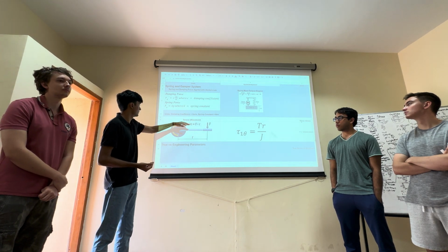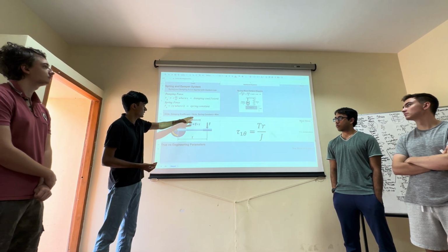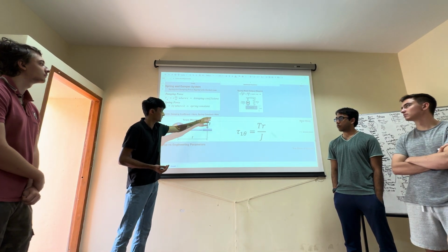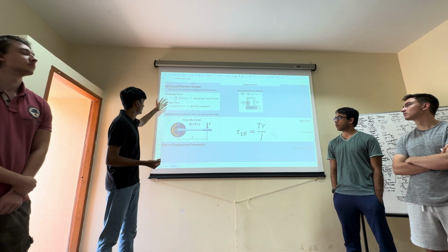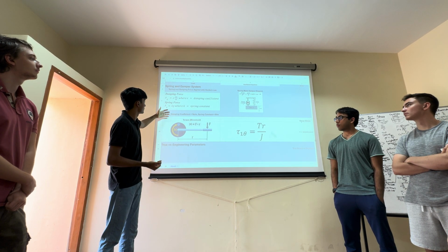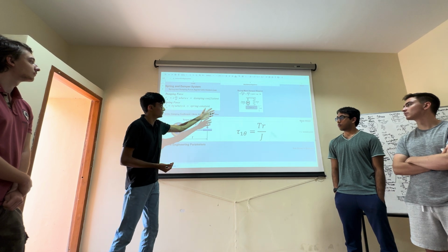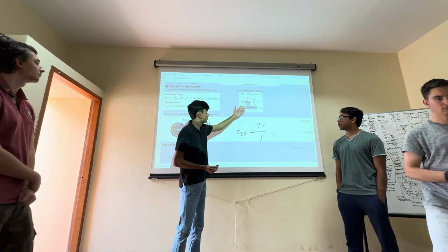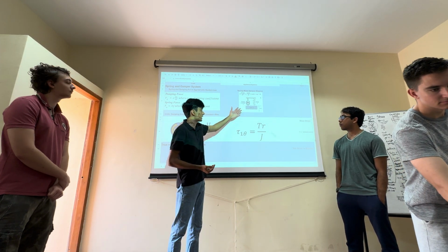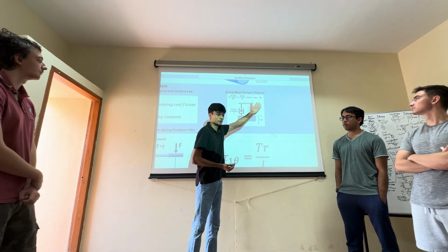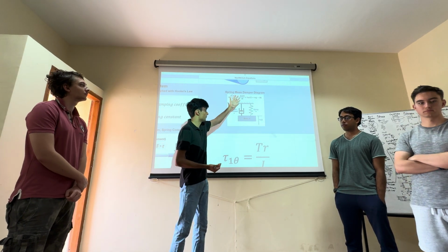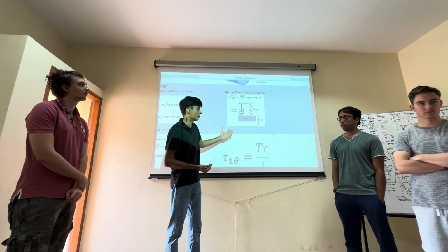That is the spring constant, so the damping coefficient is Ns over m, while the spring constant is N over m for units. And then, how do we take these forces and relate them into an equilibrium equation, so we can have a spring-mass-damper kind of system where an equilibrium equation dictates how this system behaves?